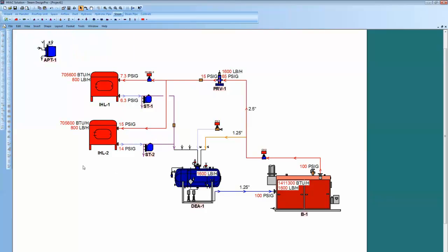So there we created a simple steam system with the 4 major system components: generation, distribution system of piping, imposed loads, utilization of some type, process there, in this case autoclaves, and then the condensate recovery with miscellaneous smaller minor steam parts, meaning the traps, control valves, PRVs, whatnot.